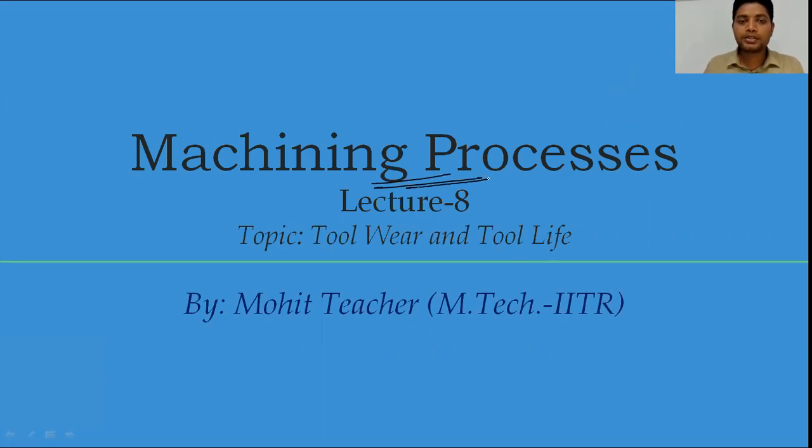And in the last video we discussed how the different types of forces that we are using in turning operations are converted into the main cutting component, that is FC, and perpendicular to that is FT, that is the thrust force. And once the conversion takes place, we saw how we can calculate the remaining forces that we have already derived for orthogonal cutting by using the Merchant theory.